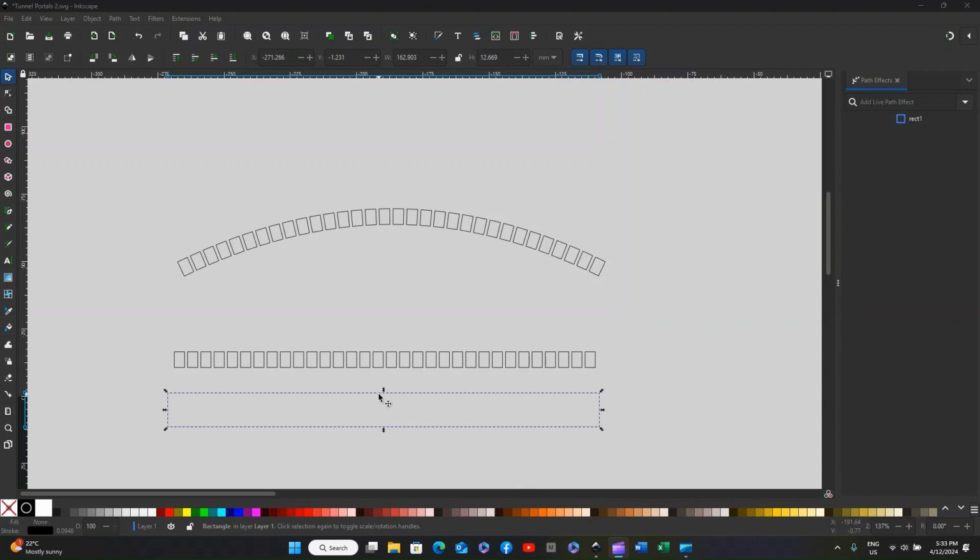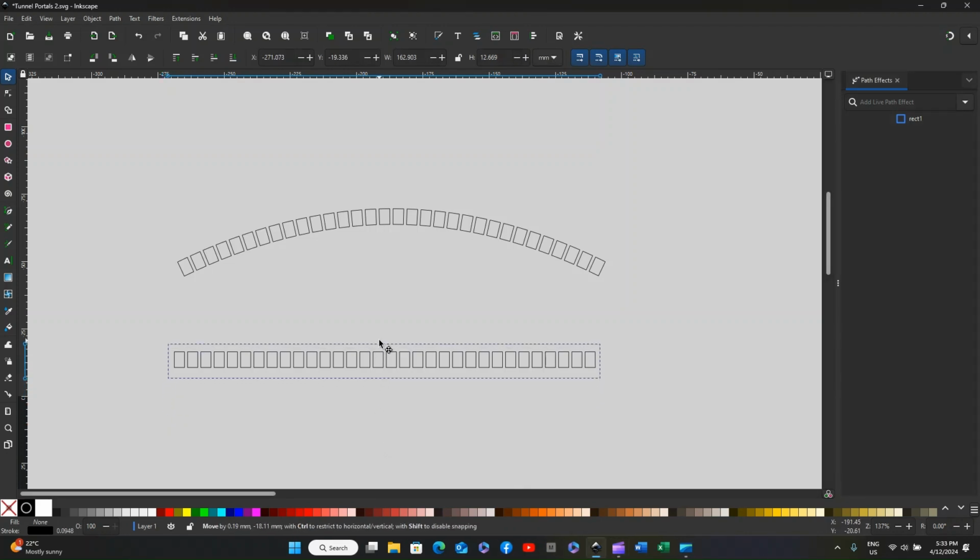If you want to, you can then surround your stones or bricks with a box so that it will also scribe this line if you set the material as half the width of what the actual material is. So as I said, if it's a 1mm material, set the cut at 0.5 and it will only scribe these in rather than cut right through.